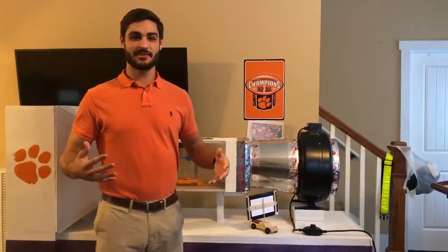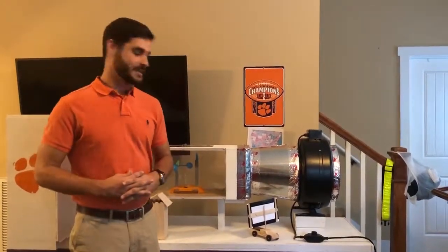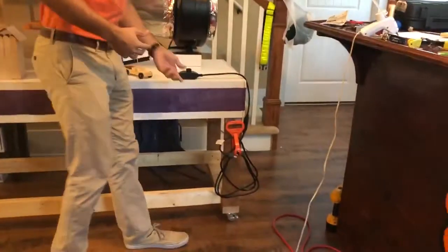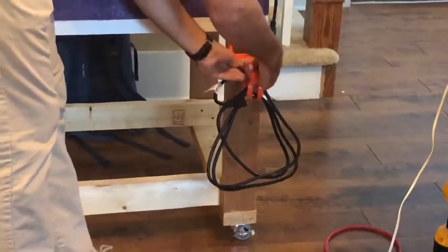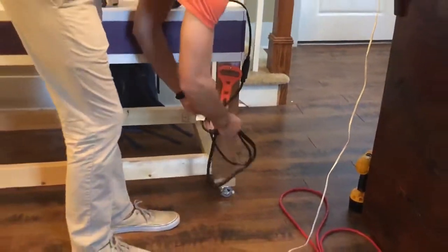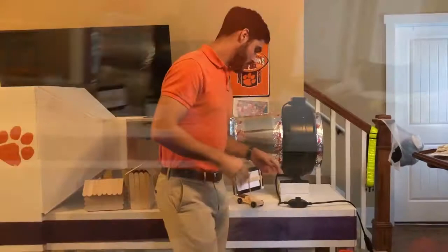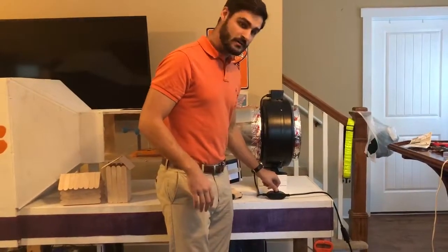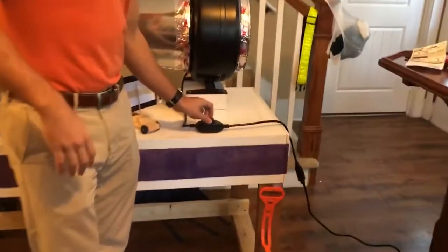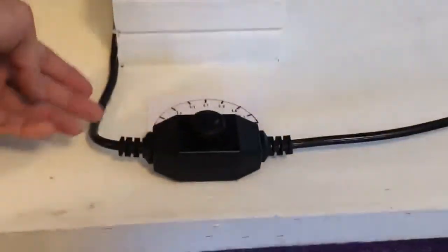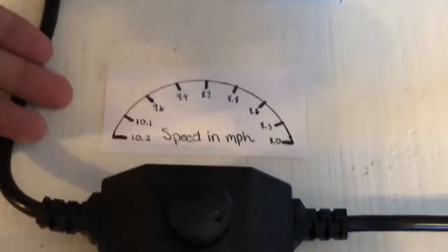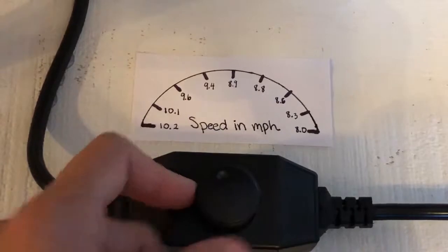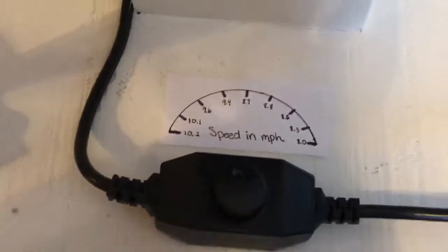Now that we've introduced the wind tunnel, I'm going to give you some key steps on how to use it. First, what you're going to want to do is put power to the fan. In order to do that, we're going to go down here and release our cable and plug it in. So I'm going to do that really quickly. You're going to want to put power to the fan by turning our wind speed dial on. Once you have it on, you'll be able to manage what type of wind speeds are going to be happening inside of the wind tunnel by dialing the knob to the desired location based off of our speed map.